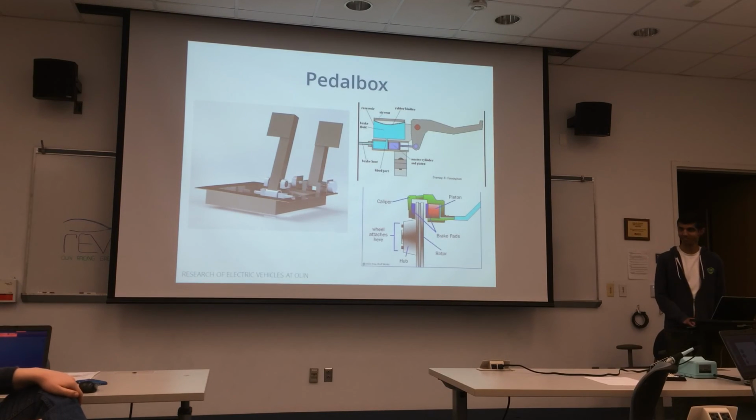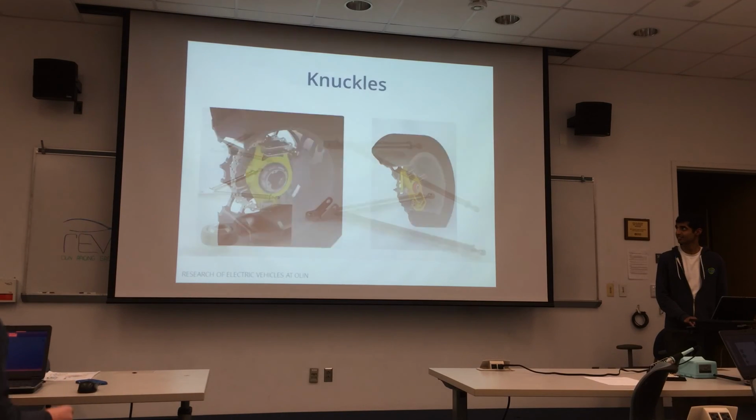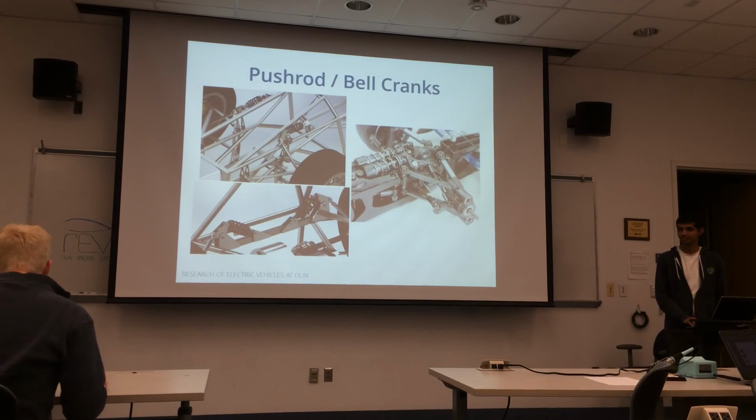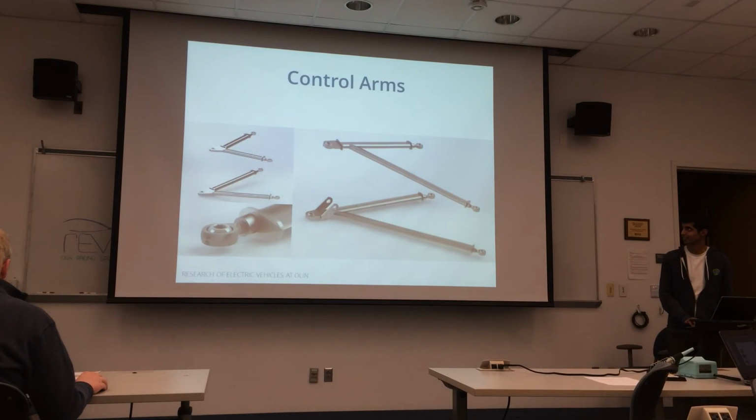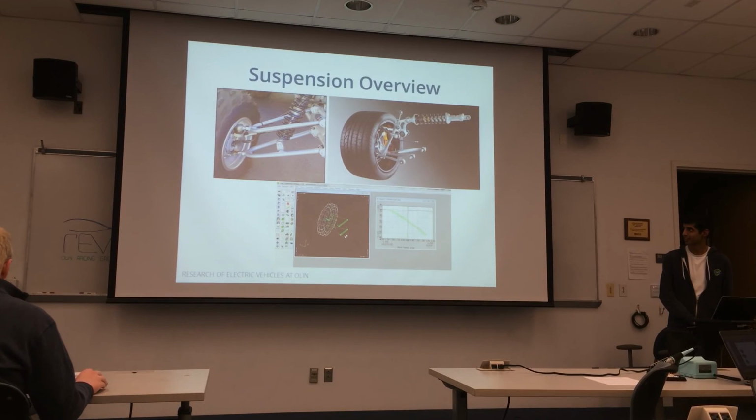Can you go back to the push rod and bell crank? What does it exactly push? She's wondering. So if we go here, you can see there's the shock attached directly to the lower control arm. So as this goes up, the whole shock will get compressed.